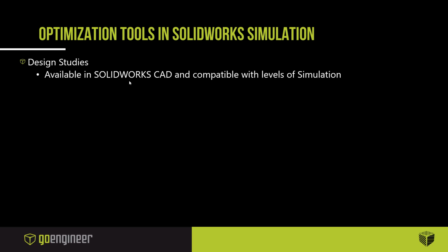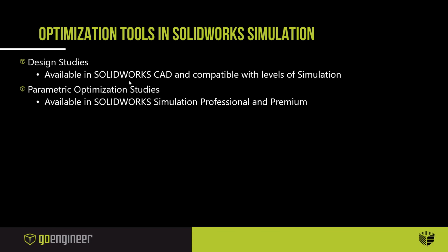Now, what are the tools in SOLIDWORKS simulation that allow us to accomplish this goal? I'm going to go on a slight little tangent here and talk about design studies. Design studies are a tool that is already available in SOLIDWORKS CAD, just regular SOLIDWORKS CAD, and it is actually compatible with all levels of the simulation product suite, be it simulation standard, professional, or premium. It's important that we talk about the features of this because of how it wraps into parametric optimization.